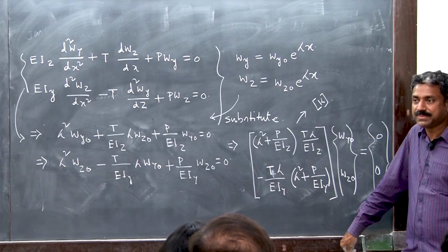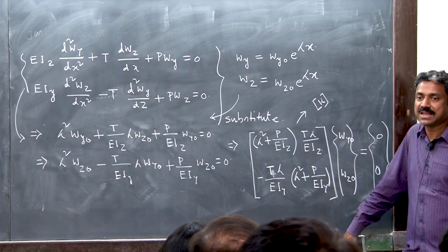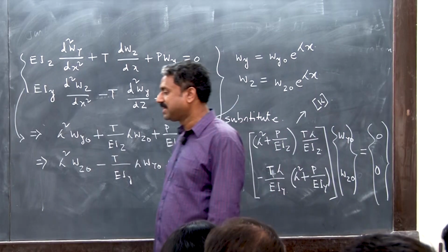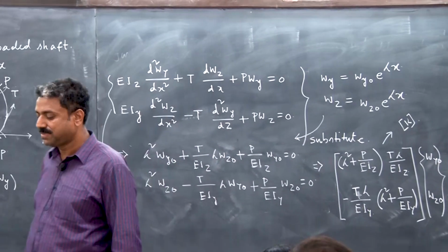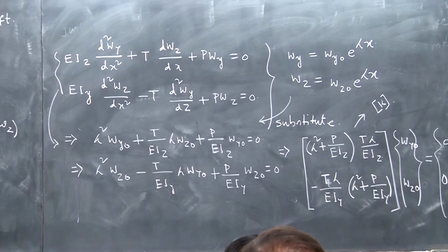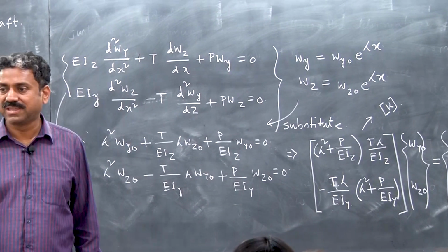Stiffness matrices are always symmetric, right? Point stiffness matrices can be asymmetric. The conventional stiffness matrix has several properties. One is of course positive definiteness, and another is that it needs to be symmetric. Why? Because of Betti's reciprocal theorem.